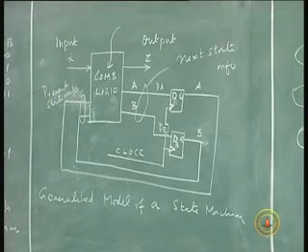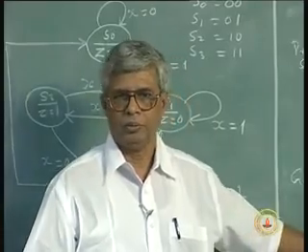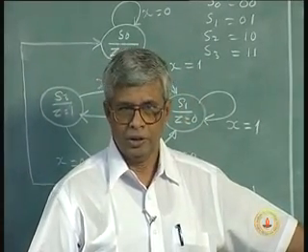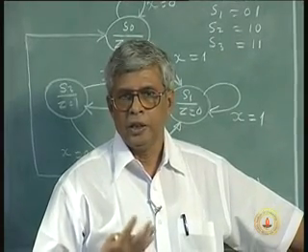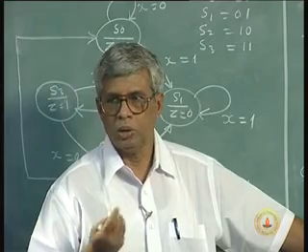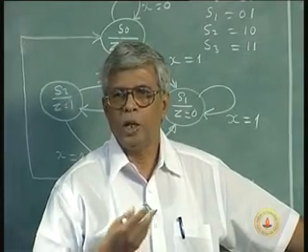It's a generalized model. A state machine. If you understand this concept, in order to design a digital system, all you have to do is to reduce it to a state graph from the behavior. Given a behavior of the circuit to you, you have to model it as a state graph.